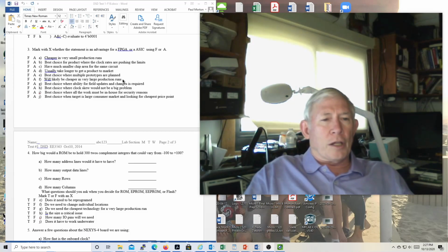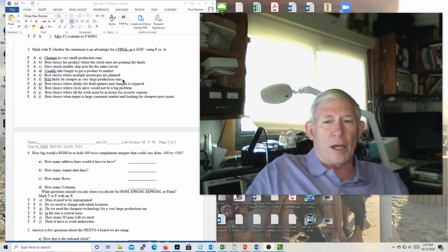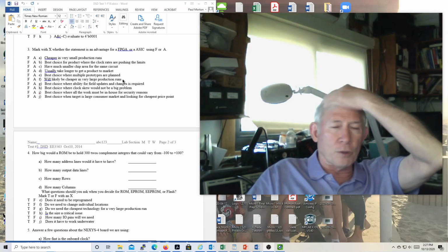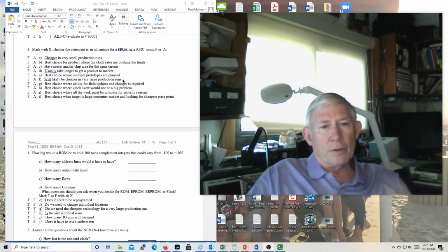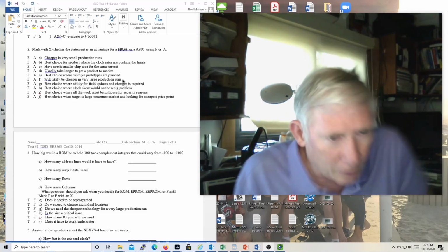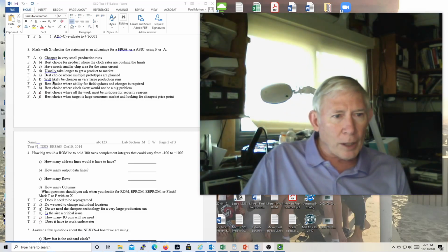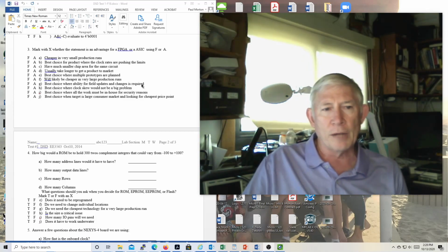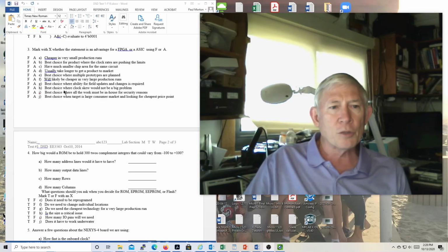Clearly, in large production runs, the FPGA is going to get pricey because they're going to be more costly per chip than what you can make to do the same thing. All right, best choice where ability for field updates and changes are required. Okay, no choice. You have to have an FPGA.